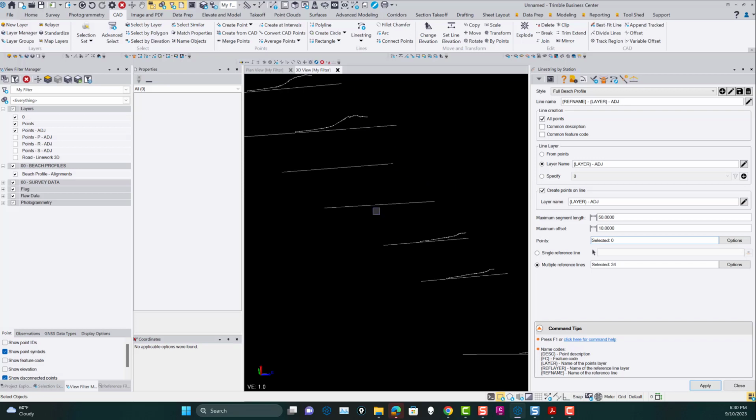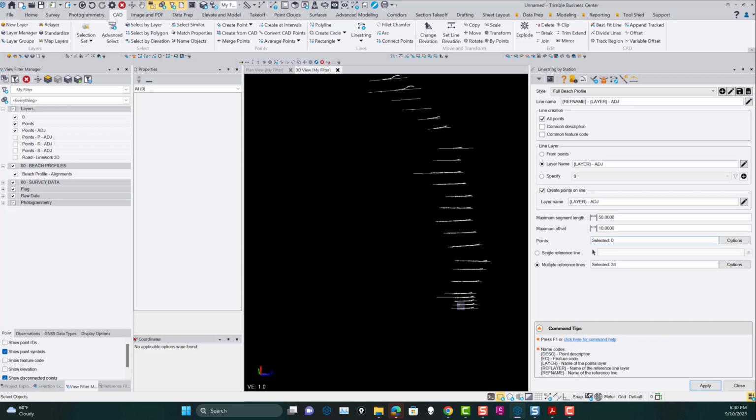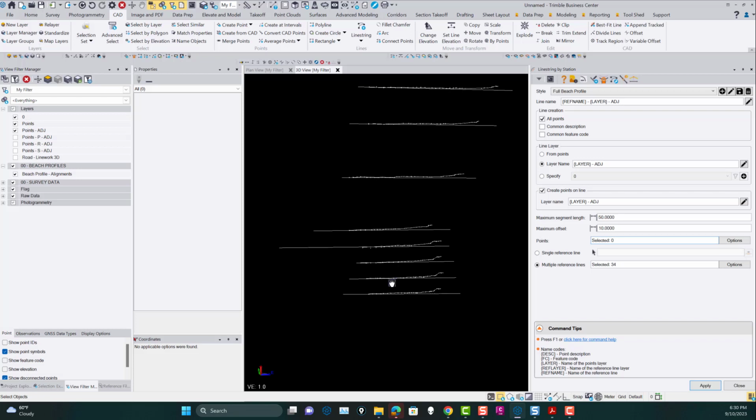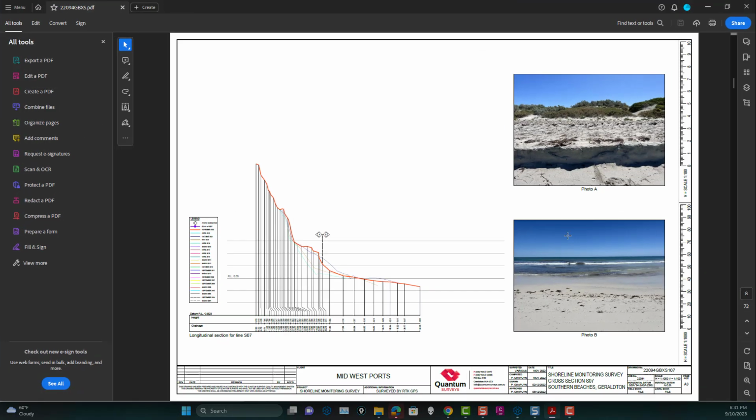And you can see now these profiles, and the goal of this is to try to produce the line work that can then be used. If we make these into corridor models, we can then use a corridor for each of these alignments and then generate profile drawings with the European or the US style profile grids with drop lines and information boxes beneath them, so that you can produce drawings that look something like this in a fully automated way.